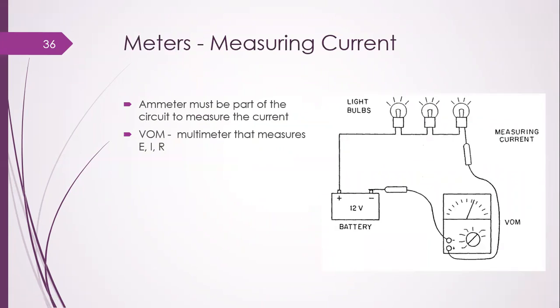the meter for measuring current, and what is the way to find the current in a series circuit. In a series circuit the current is the same, and the way by which we need to measure the current is to open a closed circuit and connect an ammeter from the ohm meter by selecting the ammeter with the selector switch, and then connect it in series with the circuit, then the current would appear on that analog screen as well.